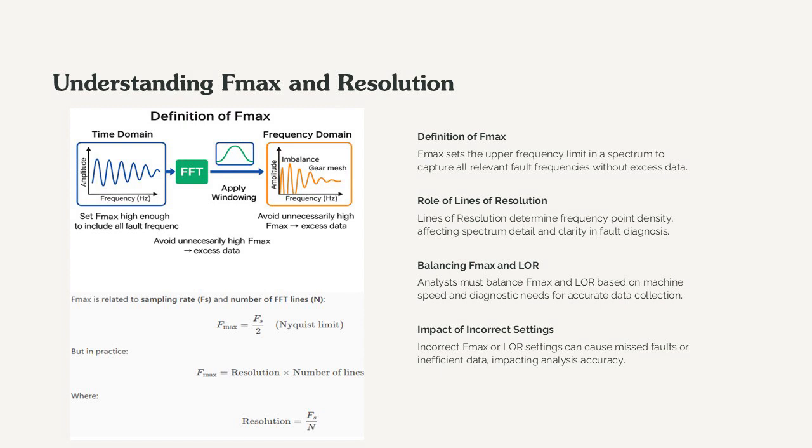Analysts must balance Fmax and LR based on machine speed, fault frequencies, and diagnostic objectives. Incorrect settings can lead to missed faults or inefficient data collection. Understanding these parameters is essential for accurate and efficient vibration analysis.